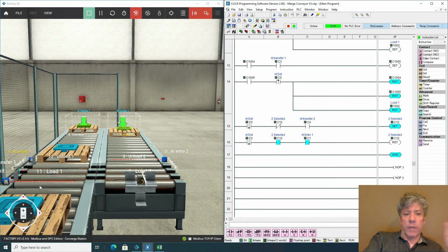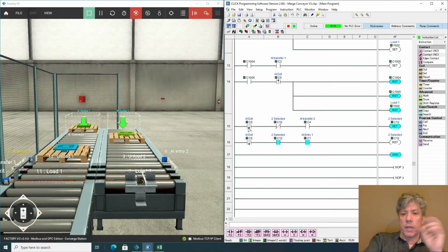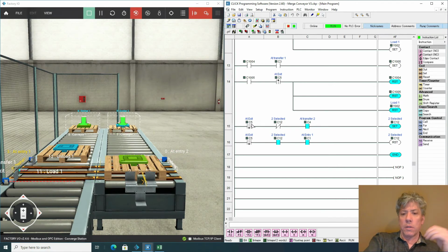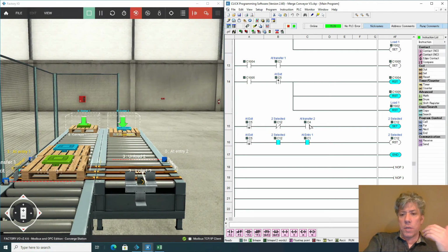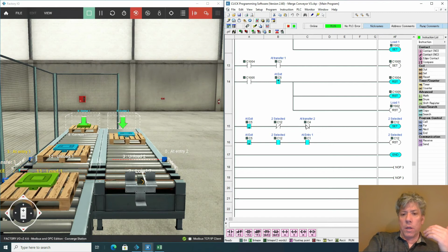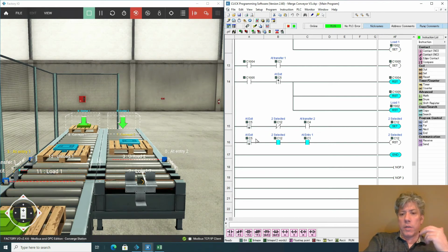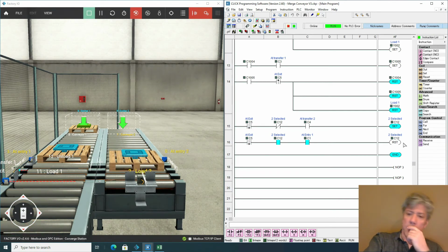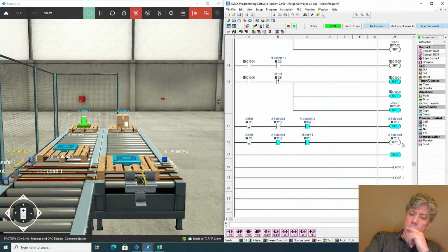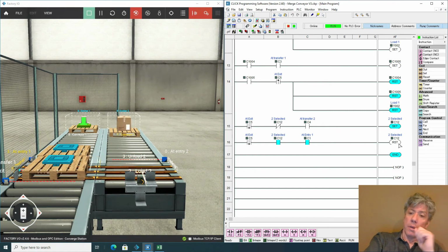This comes on whenever that sensor, that exit sensor, goes true, but it doesn't actually trigger through the rung until the sensor drops, until the falling edge occurs. So there's nothing to transfer to, and it drops right there. When it drops, that should have set this bit. Now it reset it. So now we're choosing 1.